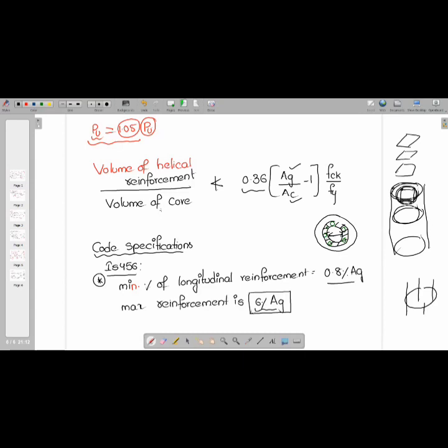Now, what I would like to tell you here is, you have mentioned that the maximum reinforcement is 6% of gross area. But for your information, even though the code says it is 6% of gross area, practically it cannot be more than 4%. Simple logic, my dear students: when you provide more and more steel, the brittleness also will increase. Agree?